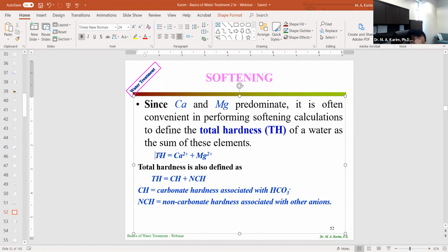So similarly, in this case, calcium and magnesium, when we measure their concentration, we measure milligram per liter as this cation. But when we add them, they are not right because they are milligram per liter as ion or things like that. We have to bring a common unit. The common unit is we can convert those to milligram per liter as calcium carbonate, both calcium and magnesium, then add them up together. Whatever total we get, we'll calculate as milligram per liter as calcium carbonate. So that's why just adding them together is not the right way to do it, but I'll explain more later.